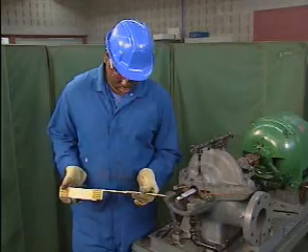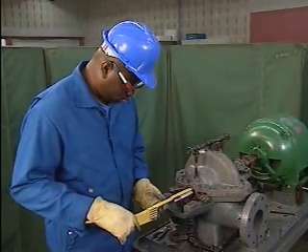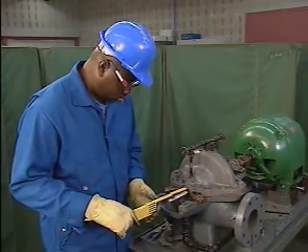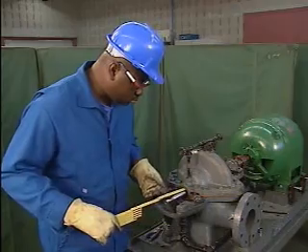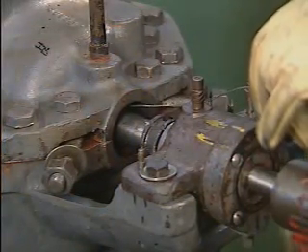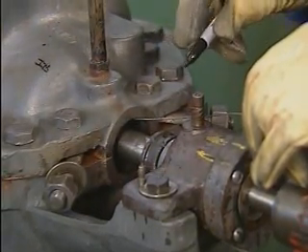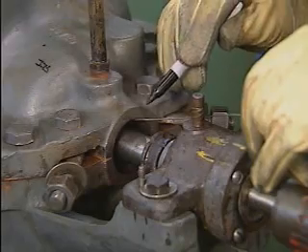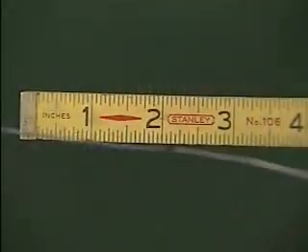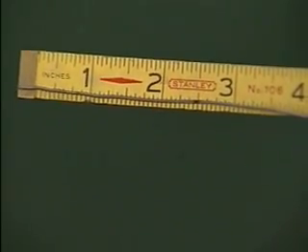Next, the mechanic uses a ruler to measure the depth of the stuffing box to determine how many rings of packing will be needed for this installation. The depth of the stuffing box is the distance, top to bottom, parallel to the shaft. On some applications, it's not possible to directly measure the depth of the stuffing box using a ruler. Instead, the mechanic inserts a stiff piece of wire into the stuffing box and marks the depth on the wire. He removes the wire and measures the distance from the mark to the end of the wire in order to get the depth measurement.